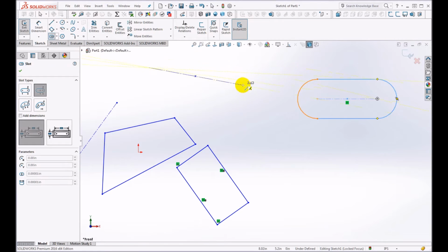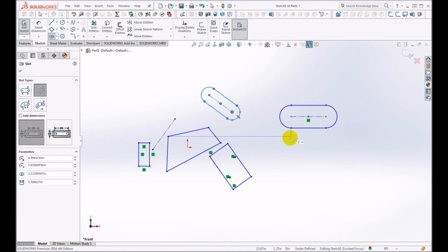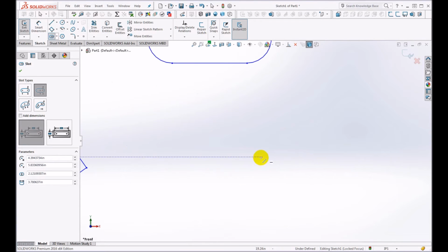So here, notice it emanates from a center point. So if you knew, for example, that you wanted a screw slot to be centered on a particular feature or point, you could use this tool, and then once again, once I plant it, I drag out to define the radii of the groove itself, click again, and now I have my slot. Let's scroll out and make a little bit of room here.